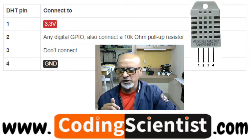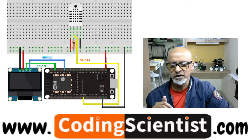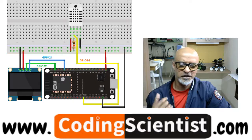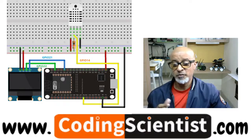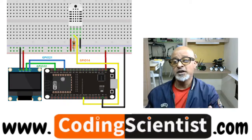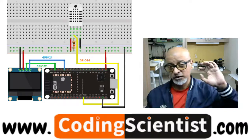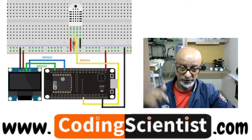So let's go ahead and hook up our circuit, guys. We need one 10K resistor because we are using the DHT11, which is very low cost, and the data may not be accurate. The most important aspect of this lesson is to understand how to program it, how to connect your OLED, and how to start reading the sensor information. In the next lesson, I will show you how to publish this information on a web browser, in real time on the cloud itself. So this is the basic lesson.